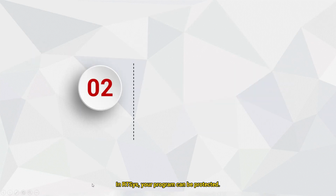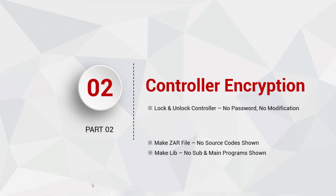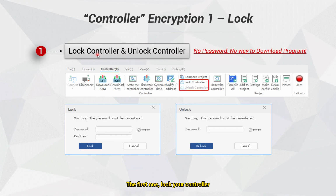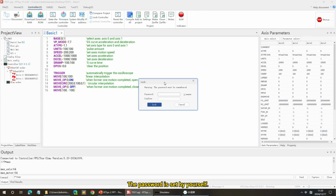In RTSys, your program can be protected. There are 3 ways to make sure of your intellectual property encryption. Number 1, lock the controller. Number 2, make your program a ZAR file. Number 3, make your program a lib file. The first one, lock your controller. Then your controller program can't be modified without the password. The password is set by yourself.